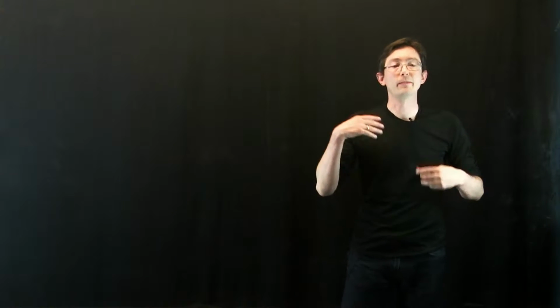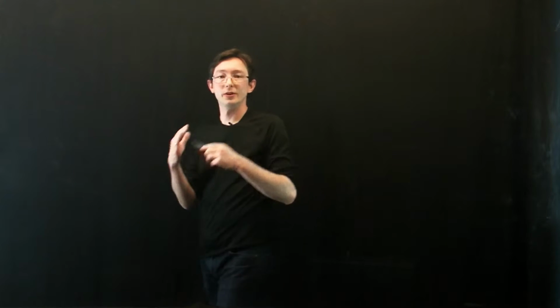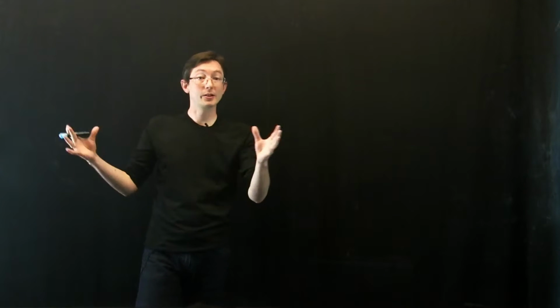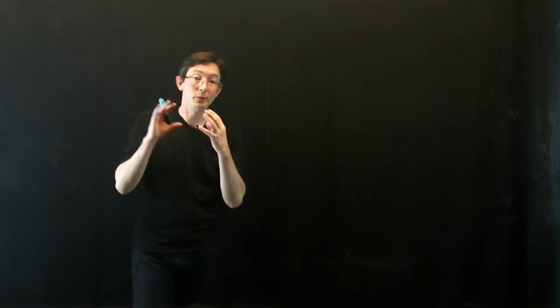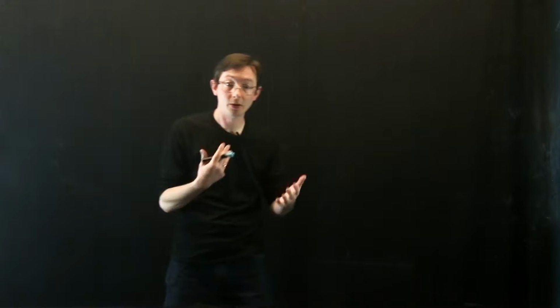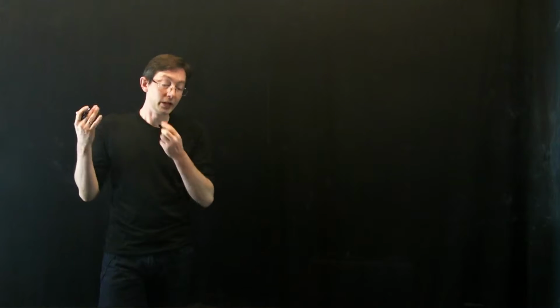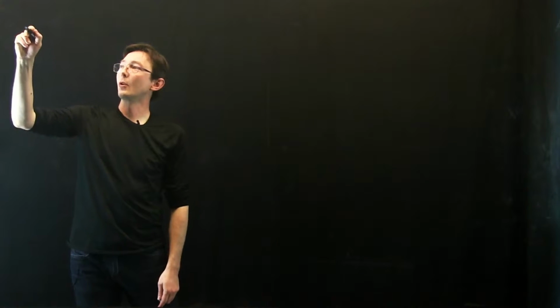Welcome back. Up until now, we've been talking about balanced truncation, which is an effective strategy of model reduction. If you have a high-dimensional system with a lot of states and you want to get a reduced order representation in terms of the most important states so that you can control it faster, we can use balanced truncation. So the basic idea here is I have some coordinate transformation, x equals T z.